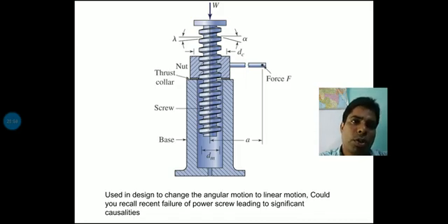If I put this spindle in rotational movement, the total mechanism gives an up and down movement, and that is the requirement. If the threaded portion moves up and down, the load is in the downward direction, because the power screw is used to lift or lower any type of load.